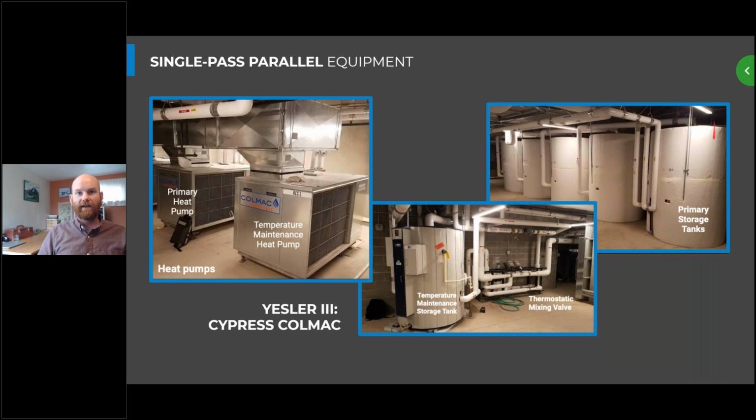And at Cypress, we have 5 storage tanks connected in series. So we have our cool tank, and then they get hotter as we go to the left. So during normal operation, all of these tanks are charged. There's hot water all the way back to this second one, or to the first one right above that temperature sensor. And then as cool water comes into this, that's going to result in that temperature sensor dropping, which is going to turn on the heat pumps, and we're going to start to recharge these tanks while hot water is going out to the building from our hot tank at the end.